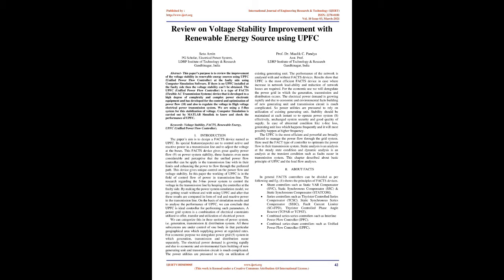In this paper, the working of UPFC is in the field of controlling the flow of power in the transmission line. The research regards the 5-bus power system, controlling the voltage in the transmission line by keeping the controller at the faulty side. By making the power system simulation model, we get results without and with using UPFC, and after that these results are compared in the form of real and reactive power in the transmission line. On the basis of simulation results and analysis of the performance of UPFC, we can conclude that UPFC is an ideal controller for performing such parameters.